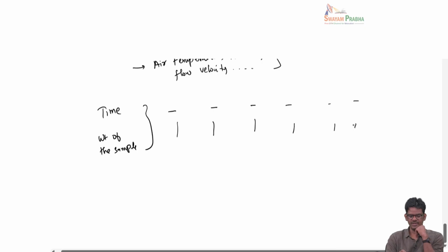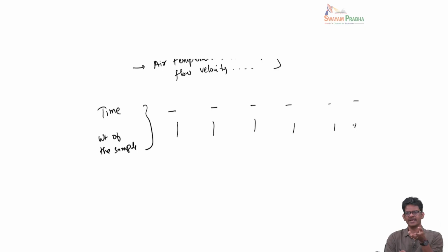And let's say you also know what is the dry mass of the solid. Okay, in the absence of any moisture, you can get that by putting the sample in a furnace and heating to a very high temperature, also making sure that the material does not decompose. So when you do that, pretty much all the moisture will be gone. Okay, and then you take that as a dry mass or bone weight. Okay, bone dry solid, without any moisture.